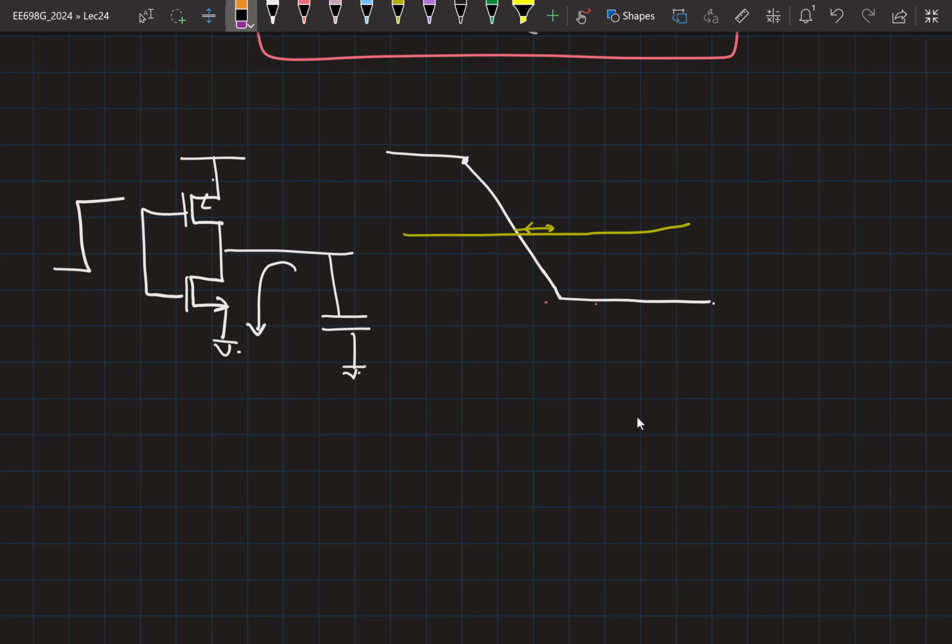But there is another factor which is causing a prominent effect. So to bring that out, let's say once it is cut off, there is no noise, like pure cut off. Then is it possible for it to contribute noise? Gate to drain capacitance. This is assuming there is a supply noise. Right? Supply noise and a capacitance.